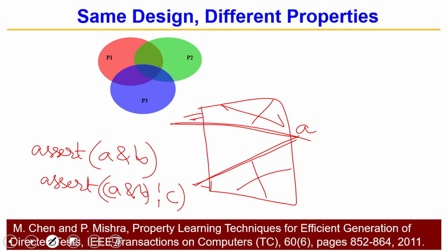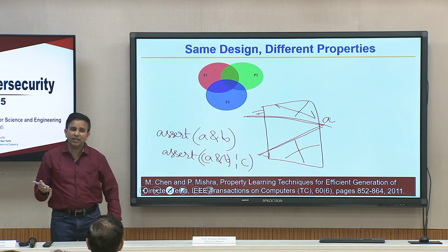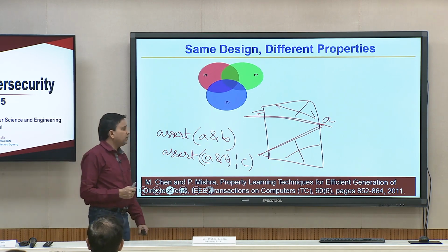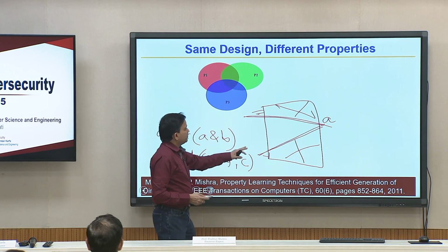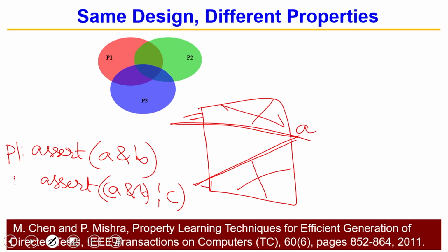You could manually slice the design and run the model checker. Most model checkers today will slice it for you, you do not have to do anything. So this is a slice for this property P1 or this assertion A1. Then for P2 it might be doing another slice, I am just randomly using a different color. So it might be making a slice of this. Then any learning or understanding you got from this part, no matter which property you solve first, you can forward to the next property.